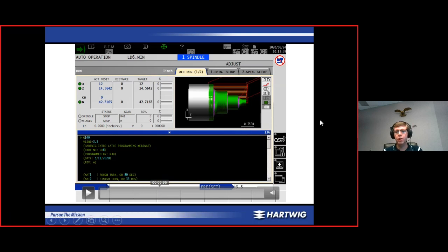You can just give a positive L for the size of the chamfer radius. On older controls, the positive or negative tells the machine whether we're cutting that chamfer radius in the X or Z negative direction or the X or Z positive direction based on the direction the tool is traveling.